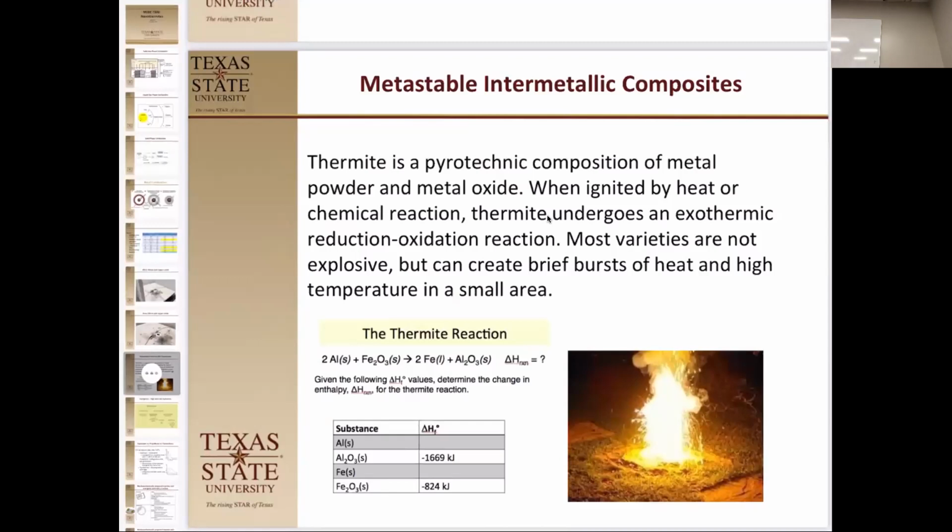Right. Yeah. I had heard of one of the vendors that used aluminum fire. It was because they were deburring sheet metal. A machine that just sands and burns sheet metal, but over many years of not cleaning the machine, somehow it can hide it. Yeah. Power. Most shops have non-ferrous and ferrous workshop areas because aluminum will do it, magnesium will do it, a lot of your softer ones, some of your nickel alloys will burn too.